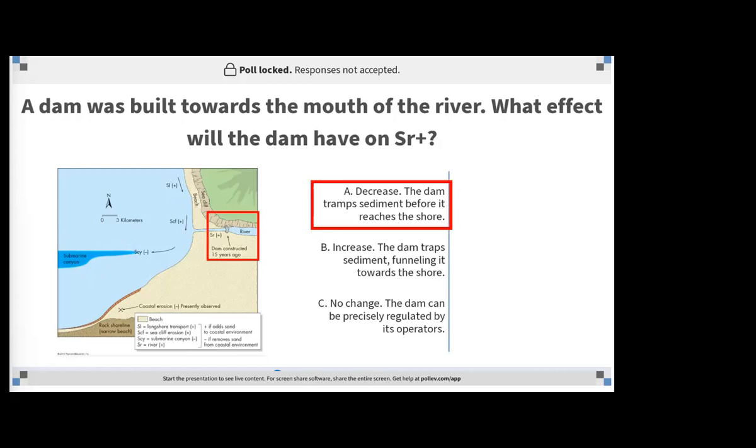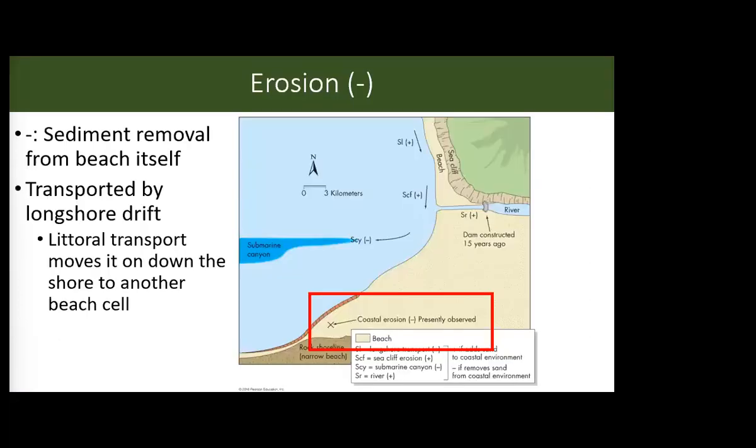This is a big problem with dam building and something that they have to keep an eye on, because if there's so much sediment built up on one side of the dam, it creates an unstable load and weight on one side of the dam. So they have to monitor sediment and calculate sediment that would be trapped in that watershed before it reaches the dam, and figure out a way to either dredge or mitigate. Maybe some of that stuff is useful. If you have real good quality clay coming out of suspension, you can use that for making bricks, stuff like that. So some of it, you have an economic advantage.